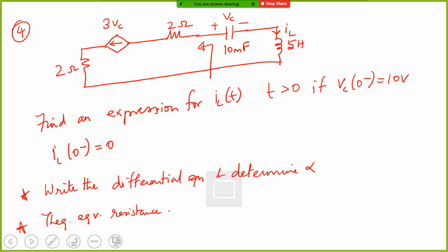So we have to look at the equivalent resistance across the series LC. Yes. That's why I gave that arrow mark. So that's one way, or you can just basically write the differential equations and determine. Both should work out fine. Basically, chop that off, put a test voltage source, okay, and you will see what is the resistance there.